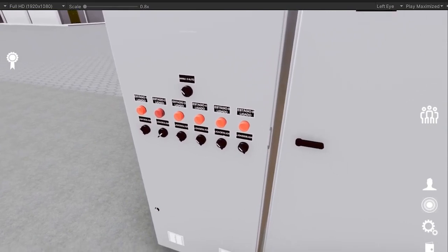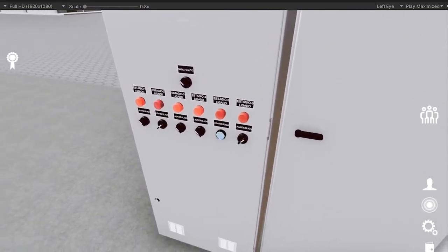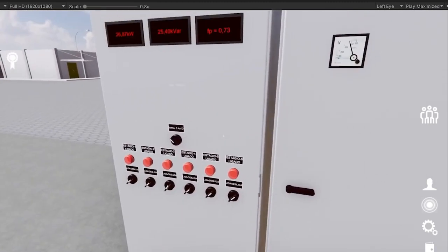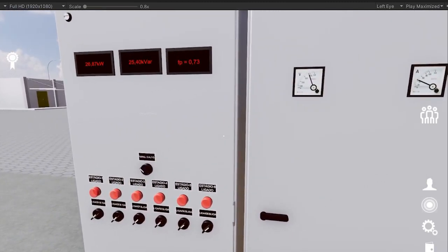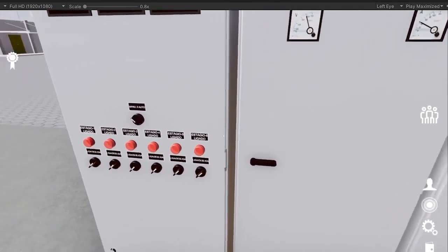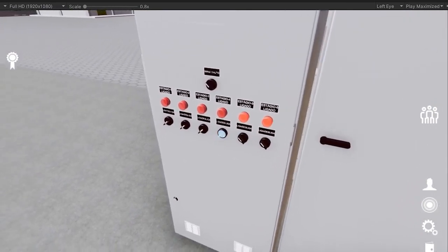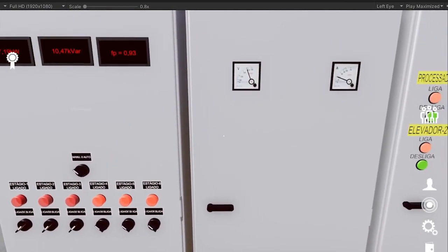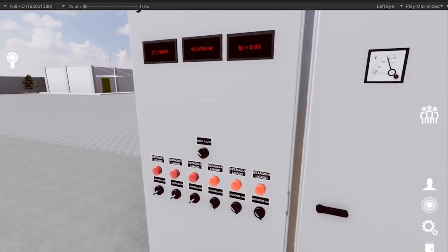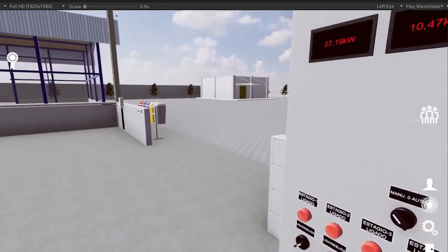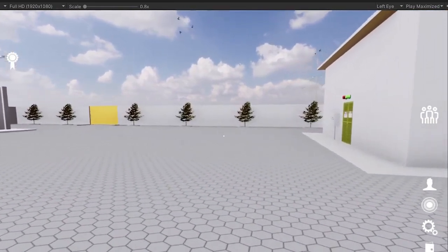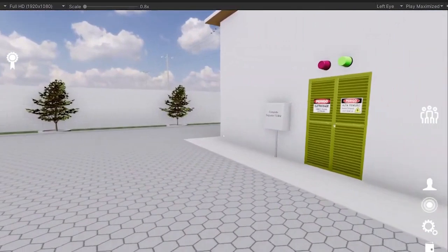This here, folks, I'm operating capacitor banks. I'm going to turn everything off. My power factor dropped to 0.73. And I have an increase in current. If I try to balance my power factor, my current drops. Anyway, folks, that's a matter of power flow. Now I'm going to shut down the factory from my primary substation.